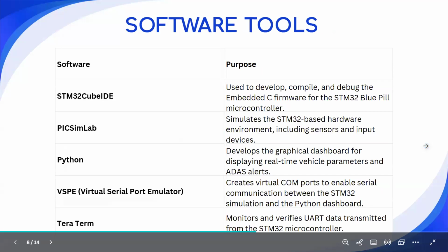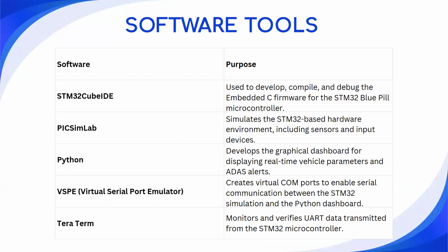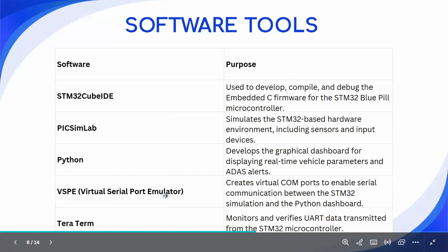Let's move on to the software tools. The software tools we have used during the development are STM32CubeIDE, used to write, compile, and debug the firmware. Proteus Lab, used to provide a virtual hardware environment for testing. Next, Python, used to design the graphical dashboard that displays vehicle information. VSPE, Virtual Serial Port Emulator, created virtual COM ports to establish the serial communication. And finally, Teraterm was used to monitor UART data during debugging and testing.